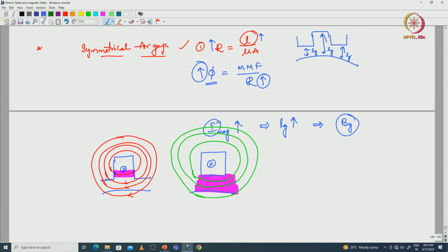And the rotor structure is here. This is the air gap. Okay. We can see here in the pink highlighted region, the reluctance will be very small, or we can say magnetic resistance will be very small. Most of the magnetic flux lines will flow in this region also. The leakage flux here is more in this condition. Here leakage flux is less,